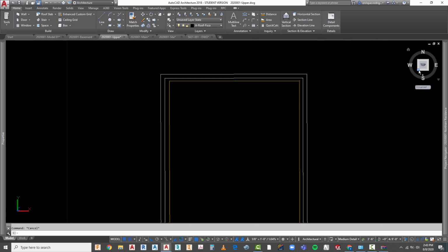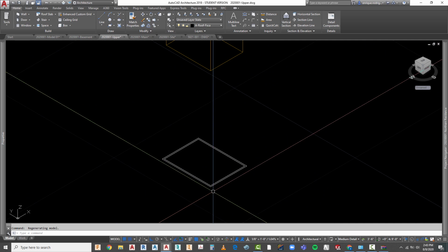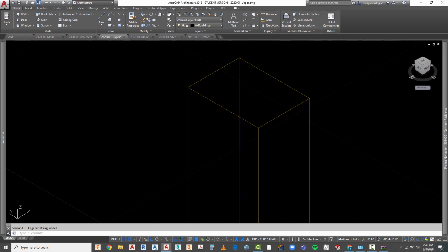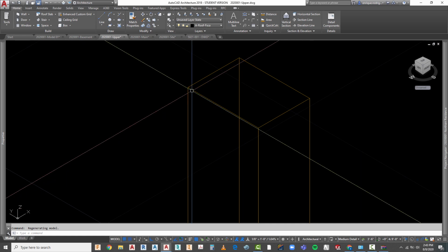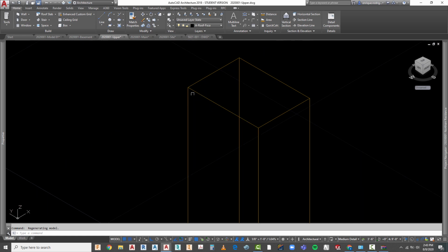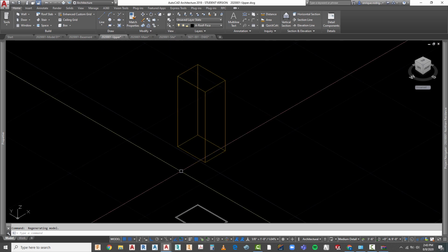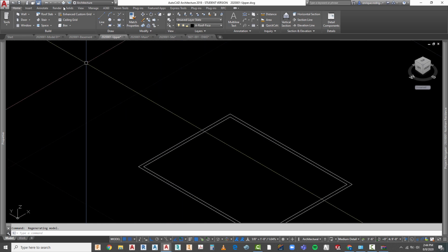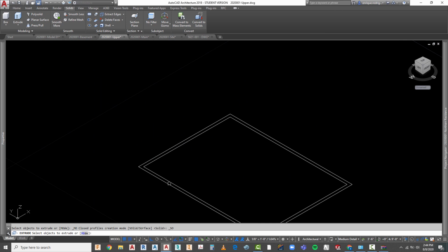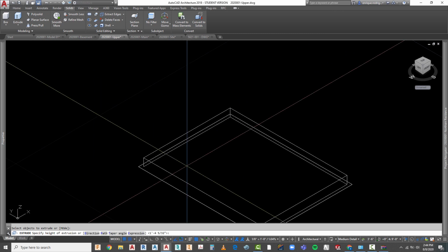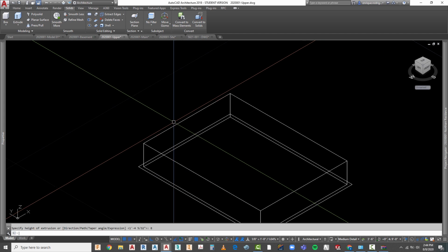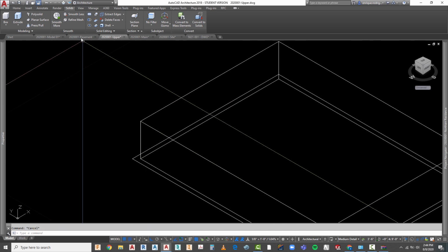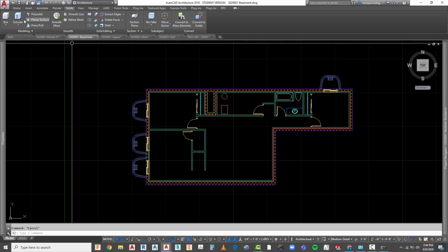So the first thing I want to do, and this is just going to be some very quick work, is create a trim work around the top. The base one, I want it to be roughly about 6 inches or 8 inches deep, and then the second one's going to be 4 inches. So let's go to solids, and I'm going to extrude the inside one, and move that up. I said 8 inches, let's go ahead and do that. And then this one I want to extrude also.